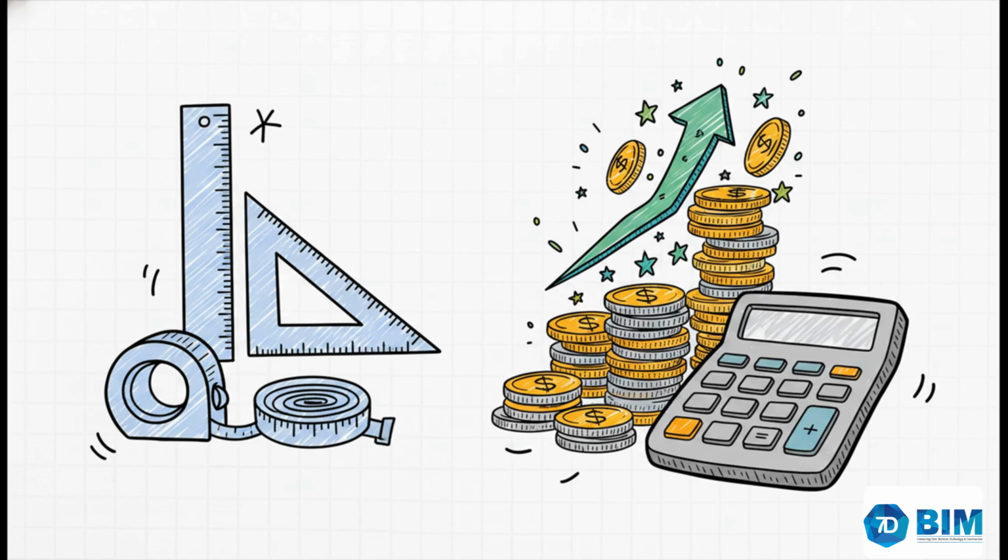Whether you're using Imperial for a US project or metric elsewhere, you need to define the specifics for length, area, volume, angle, slope, the whole shebang. But here's a massive pro tip for you. Notice that currency is on this list. Adjusting that regional currency setting right up front acts as a huge time saver when you start running cost estimations later. It's a tiny touch, but it pays massive dividends.